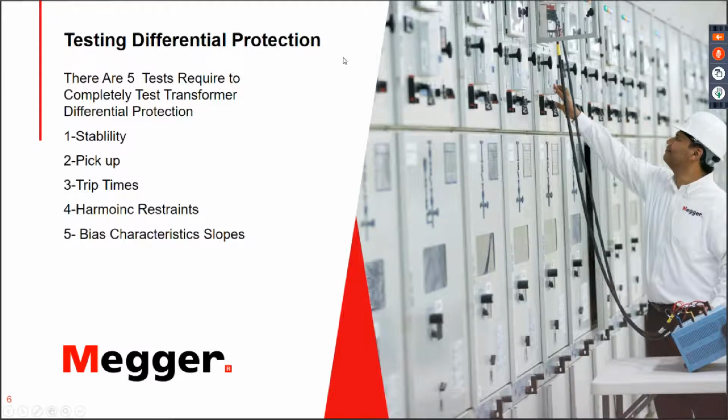For testing differential protection, there are usually 5 tests required to completely test a transformer differential protection. These 5 tests are as follows. First, we have a stability test, where we test the stability of the relay during a through fault, or what we call an outside of the zone fault, to see that it will not have any mal-operation or unstable values during this fault, or even during normal operating conditions. When there is no fault, it should be stable and not mal-operate when you have full load or a slight overload as well.